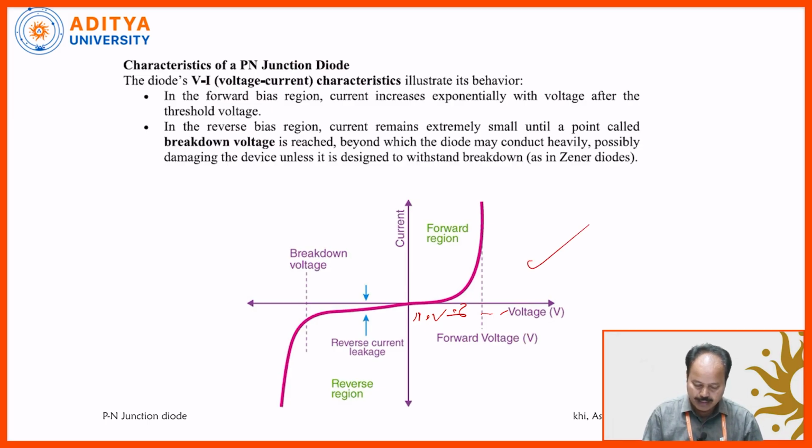So we get a curve like this, and as we are increasing the forward voltage, the forward current IF is increasing. Up to a certain voltage it is not showing anything, almost zero. Afterwards it increases a little bit, then suddenly it reaches almost infinity. Extrapolating this, it will cut the x-axis, and it will show the barrier voltage or built-in voltage or cut-in voltage. This is called the forward characteristic. Under forward bias we get it like this.